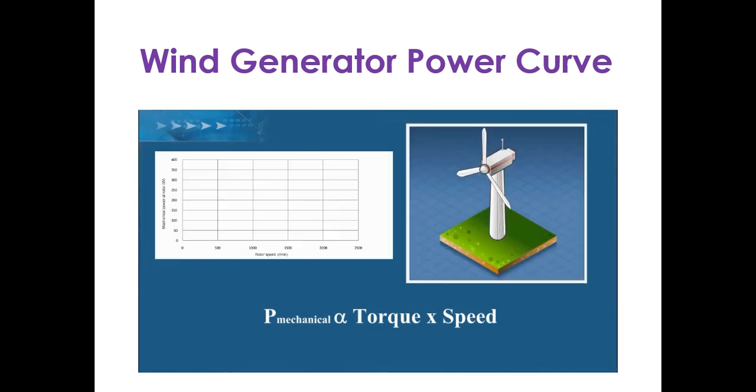When there is some wind but not enough to make the blades turn, torque is applied on the generator's shaft. But even if there is torque, if the speed is 0, the generator doesn't receive any mechanical power. Now if I let the blades rotate freely, they won't go to an infinite speed. At a certain point, the friction will bring the available torque back to 0. The power available to the generator at this point is also 0 since I have speed but no torque.